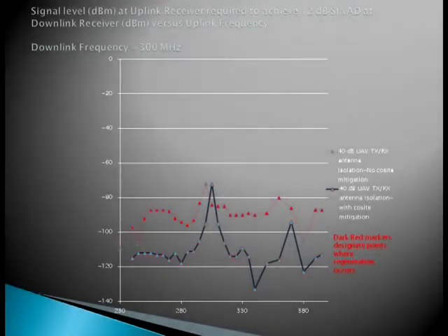This chart shows data derived from the same setup as the previous chart, but for various frequencies in the UHF band with a fixed mid-band downlink of 300 MHz. While we can see that significant uplink receive desensitization occurs due to Cosite interference, as in the previous VHF results, the UHF results raise an additional issue for relays with insufficient isolation between the uplink and downlink antennas.